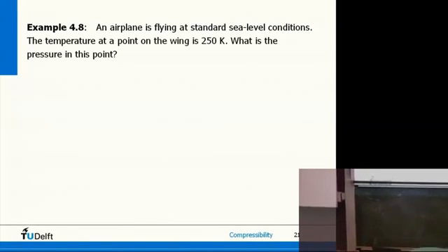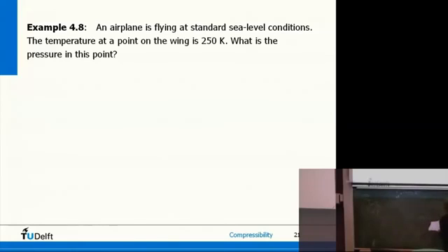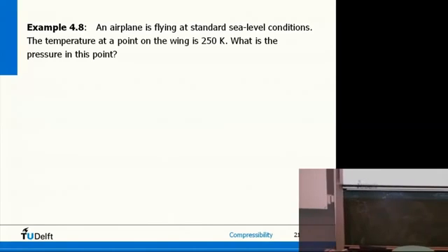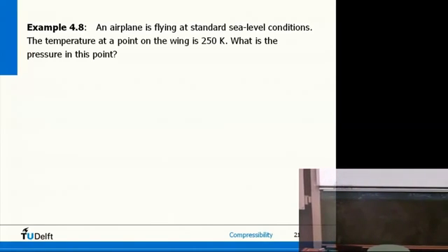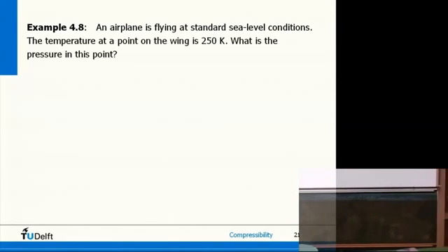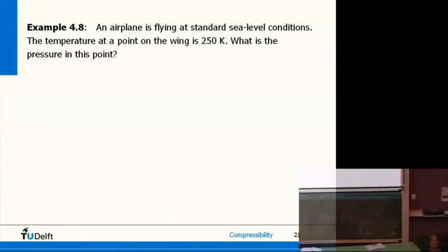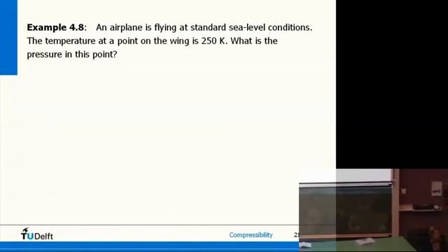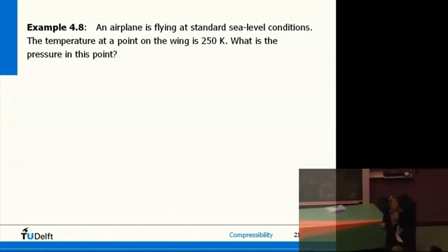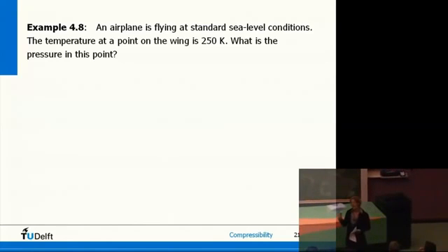So the first step we need to do is make an assumption, right? Assume isentropic flow. Does that make sense? Well, we're not heating or cooling the flow. When an aircraft flies, we can have temperature changes inside the flow, but due to the flow quantities, pressures and densities changing, we don't heat it. We don't have a fire or a cooler. Friction is also negligible because we don't look inside the boundary layer. So this point is outside the boundary layer, so we can assume isentropic flow.